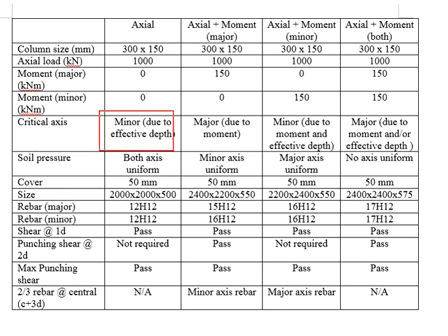Knowing that the minor axis will be more critical, if you design the calculations based on the minor axis, based on the calculated reinforcement bar, you will propose the same in the major axis. The pad footing will still be safe. If you check the minor axis passes, use the same design in the major axis, it will definitely pass.